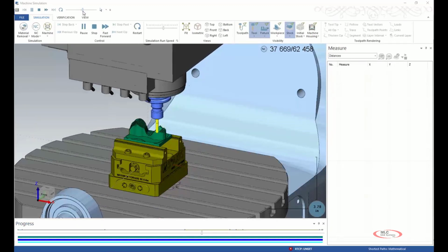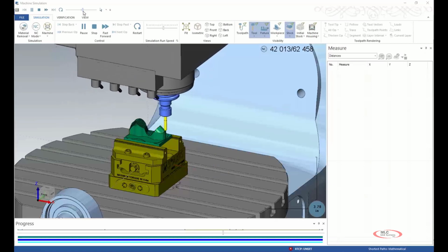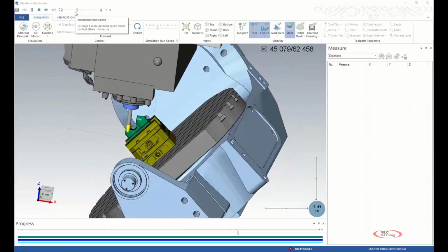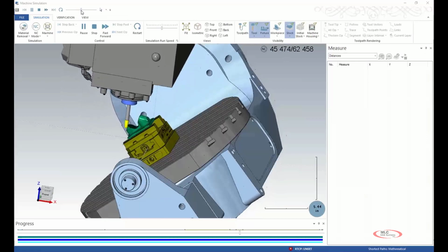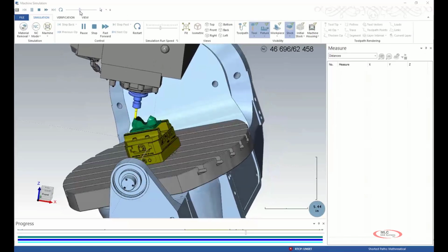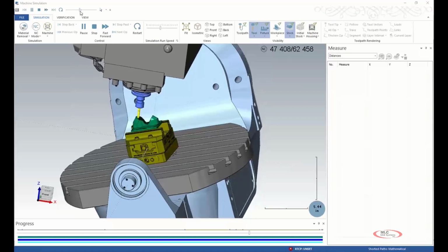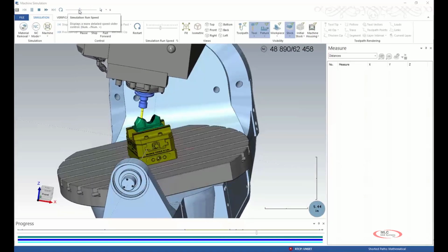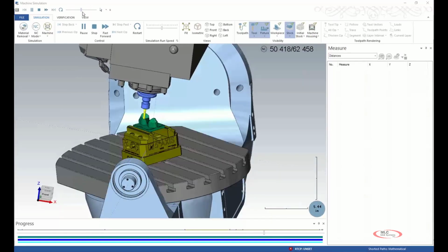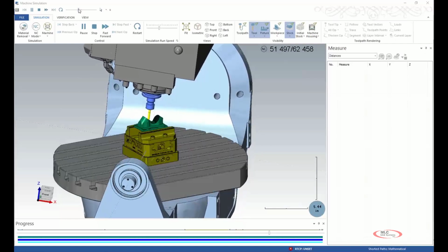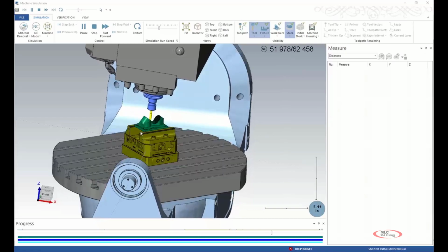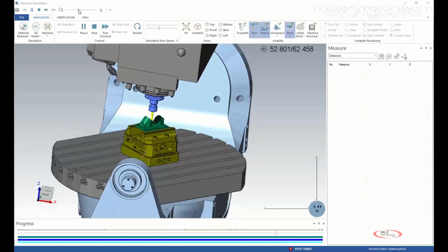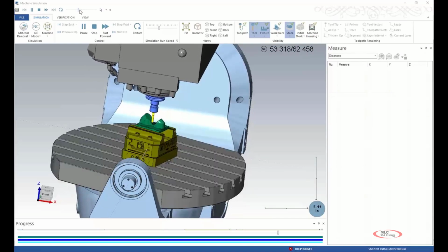So we'll go ahead and move forward with our toolpaths. And I want to point out why the simulation for Mastercam is important whenever you're doing multi-axis toolpaths. So right here, we can already see the tilt angles of my tools. And we have the ability to see if they're colliding with our material here. But notice what side this tool is on when it's surface milling this middle surface here. And once we get to about the center of this table, I want you all to pay attention to what happens.